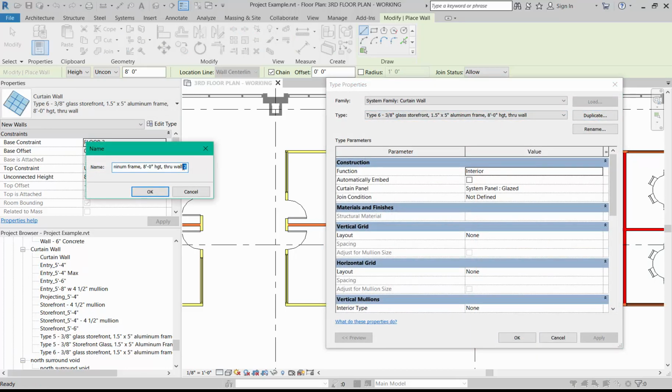Now this is still going to be through ceiling, so through wall. Wall goes through ceiling. Let's actually call it through. I'm going to keep it at the same height, but I'm getting rid of the aluminum frame. So I'm going to call this frameless. Frameless still has a channel it's embedded in, and also because it's frameless and I want better sound protection, I'm making it half an inch, which will allow me to make it a laminated glass. And as always, make sure to adjust the type.